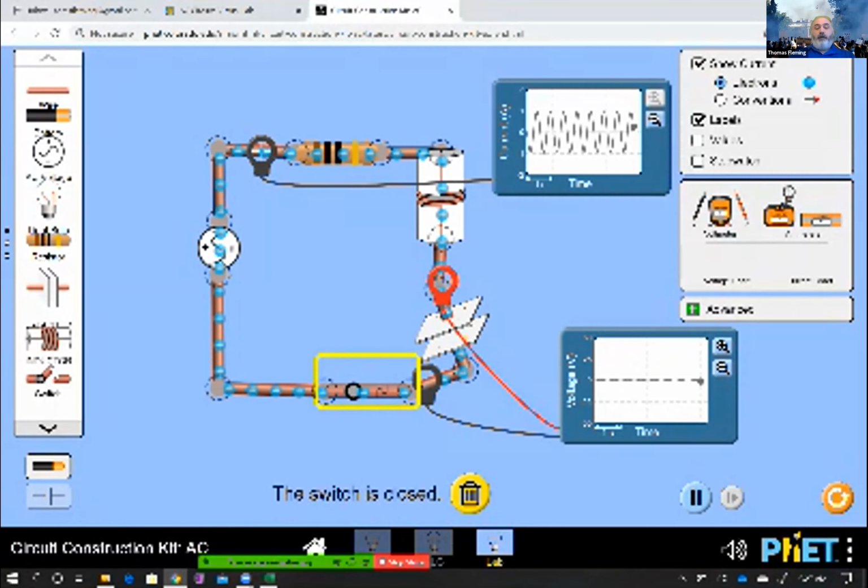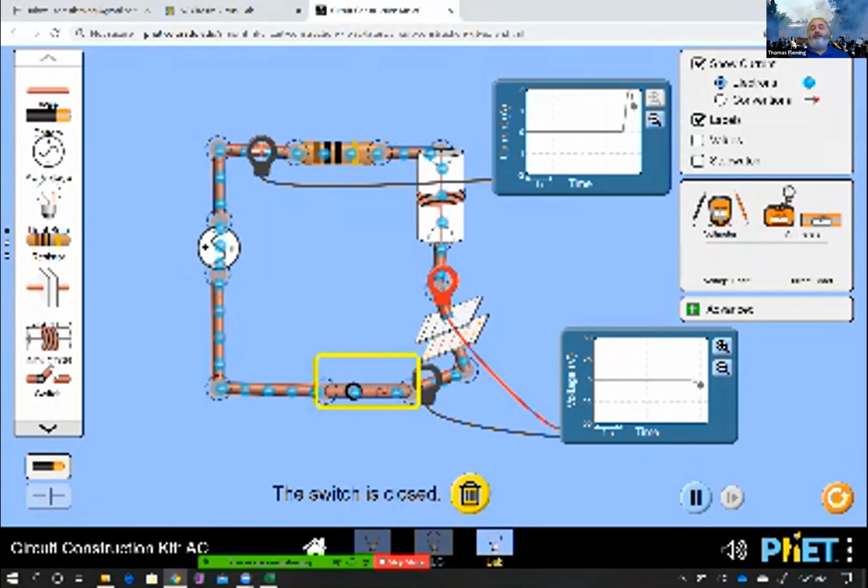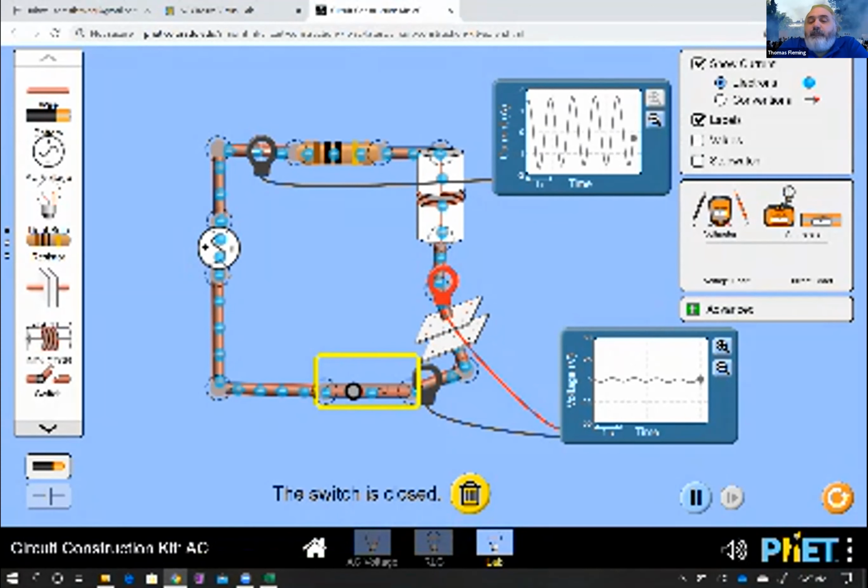If you simply take this and drastically alter your frequency, it tends to behave very erratically, because you've got an additional source of voltage besides your power supply, and that causes it to drift in a difficult to manage fashion. So just be aware of that.